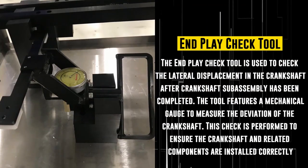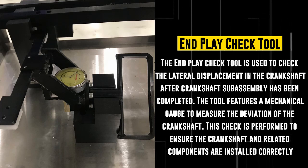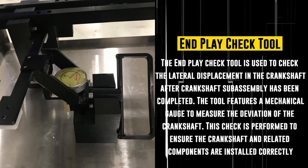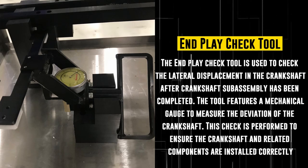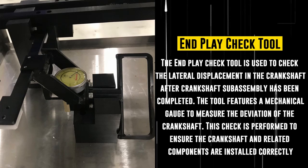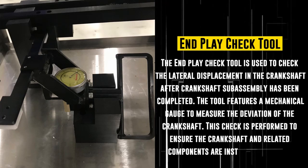End plate check tool. The end plate check tool is used to check the lateral displacement in the crankshaft after the crankshaft subassembly has been completed. The tool features a mechanical gauge to measure the deviation of the crankshaft. This check is performed to ensure the crankshaft and related components are installed correctly.